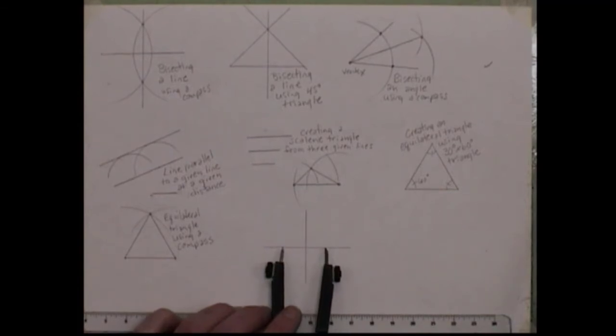So I want you just to take your compass, and I want it to be within the center mark lines. So something like this, where we make sure that we're drawing this circle within the center marks. We could go back and make our center marks bigger if we needed to, but this is just going to help you out.